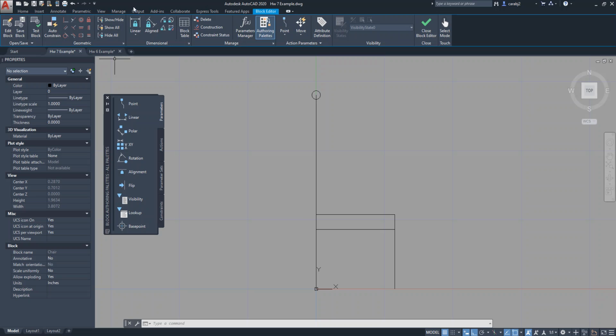Like if you create a parametric block, let's say with a dimension that you want to change, and every time you actually changed it in your original drawing, it would give you that new function. So it's just a parametrically editable block, and that would be found over here in your parameters manager, but that gets a little bit complicated. I just want to show you the basics of it. So this is the new window, the block editor window.